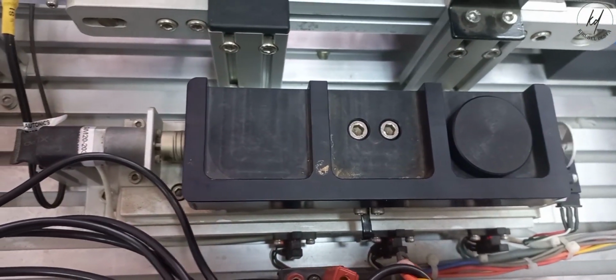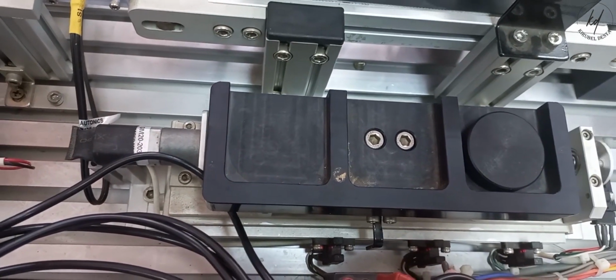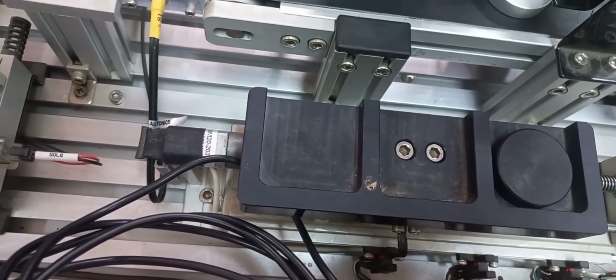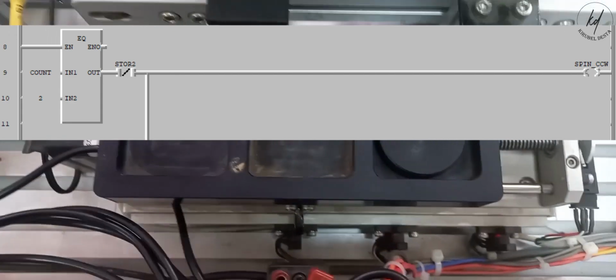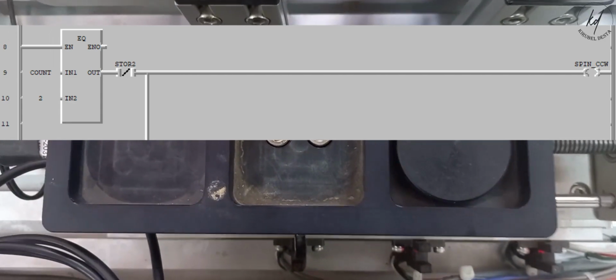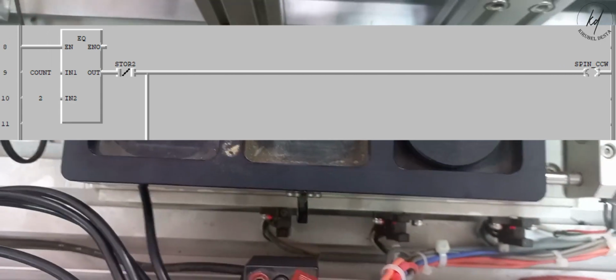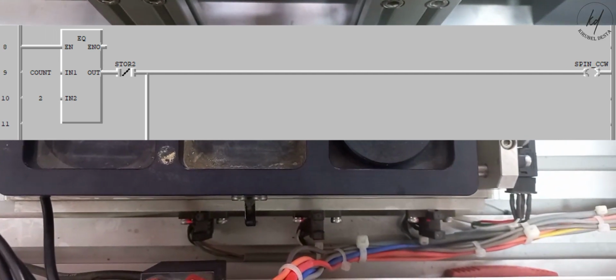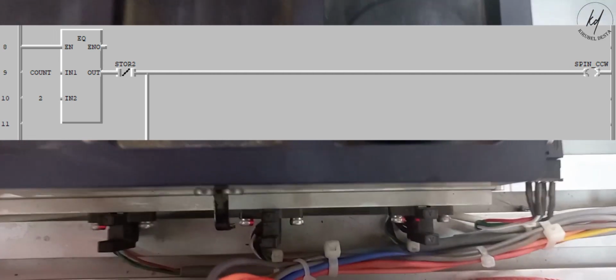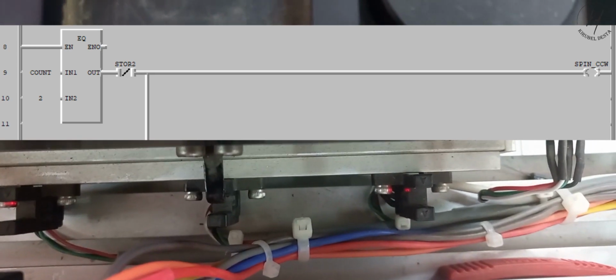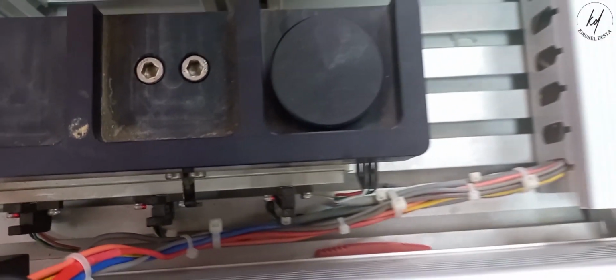The motor had been rotating clockwise before. As the push button is pressed for the second time, the count value is now 2, which goes to row number 8. As a result, the motor spins in the anti-clockwise or counterclockwise direction, and as its rotation continues and it reaches the second position sensor, that will immediately cease the motor's rotation, otherwise it would proceed with its rotation.